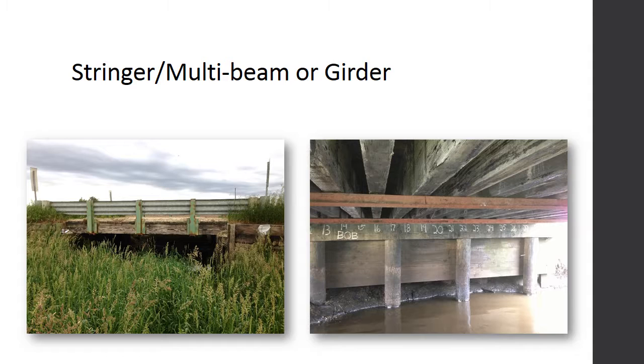Glue laminated beams, due to the method by which they are manufactured, have the ability to span much longer crossings than full sawn timber, 20 feet to 80 feet. They are manufactured from 1.5 inch thick construction lumber laminations that are face laminated on their wide dimensions using waterproof structural adhesive. The widths and depths are easily optimized for the span and design loads. The total number of beams is often fewer than that of a full sawn timber bridge construction. Originally, the glue laminated beams were treated with creosote, with more recent use of chromate copper arsenate or copper naphthenate.